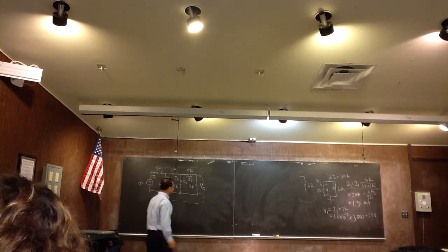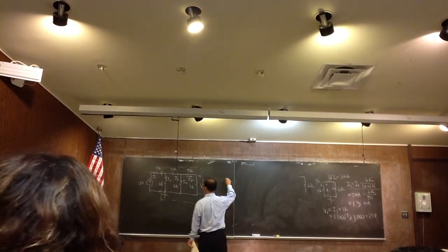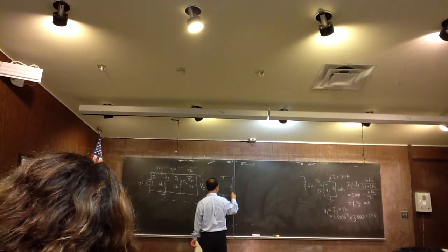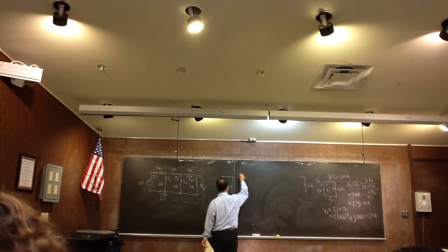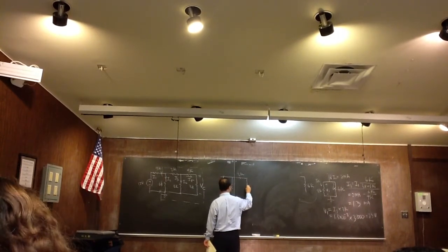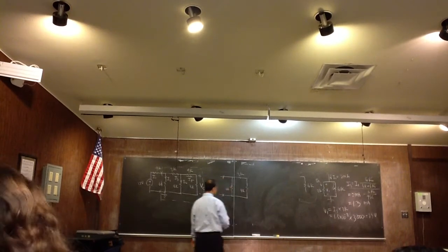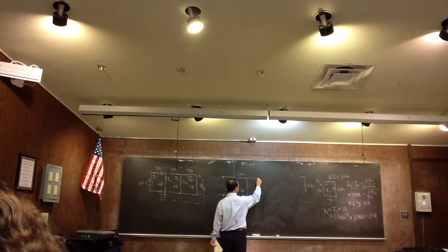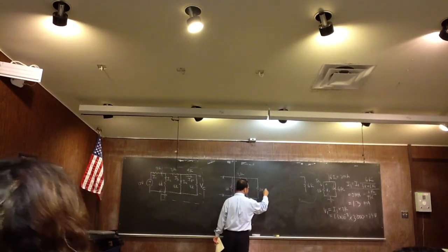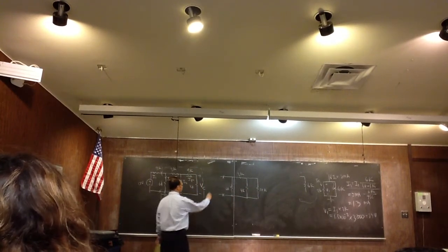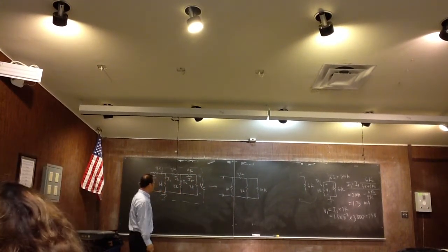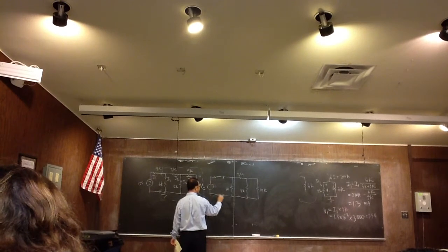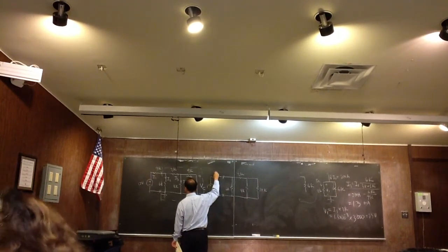These two are in series, yes? Let's mark the terminals here. You have 6K, you have 3K, you have 4K. So far, I have not changed anything. Now I'm going to combine these two and make it 12K, correct? You still need that 9K, don't you? That's outside the box. That's 9K, yes?